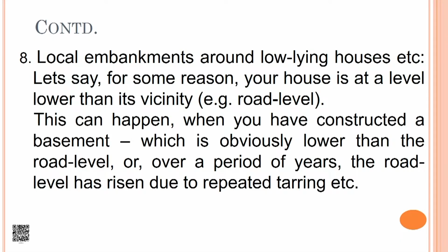Local embankment around low-lying houses. For some reason, your house may be at a lower level than its vicinity. This can happen when you have constructed a basement which is obviously lower than the road level, or when over a period of years the road level has risen due to repeated tarring.